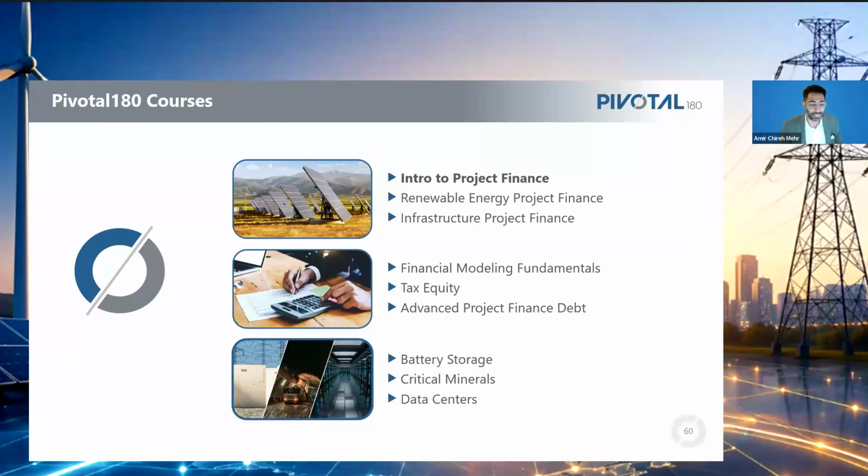So the spark spread, and you also have the black spread. So black spread's for coal, the spark spread's often used for gas. Those are industry metrics terms that are used to describe the effective profitability, say, of a natural gas power plant. It's the spread between the cost of the fuel, right, and the market price effectively for that specific power plant, given its efficiency, right, that allows you to determine whether it's going to dispatch or not, all right?